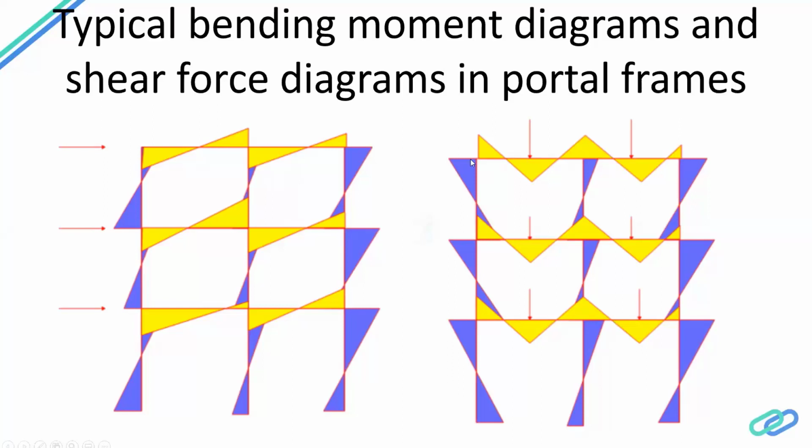And the reason for that is, if you go back to the differential equation that we were talking about, ∂⁴y/∂x⁴ is equal to loading intensity over EI. Since here there's no loading intensity as such, we don't see that continuity, but once you have linearly varying load or maybe uniform load, you will see much more curved bending moments instead of these linear lines here.